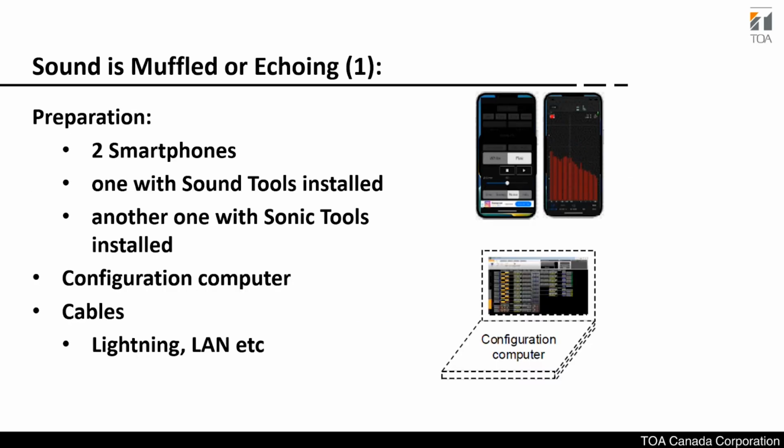So the next frequently encountered problem would be sounds being muffled and echoing. Same as before, you have to prepare two smartphones, one for signal generating and the other for reception for doing the testing. In addition, you will also prepare a configuration computer for the EQ setting.